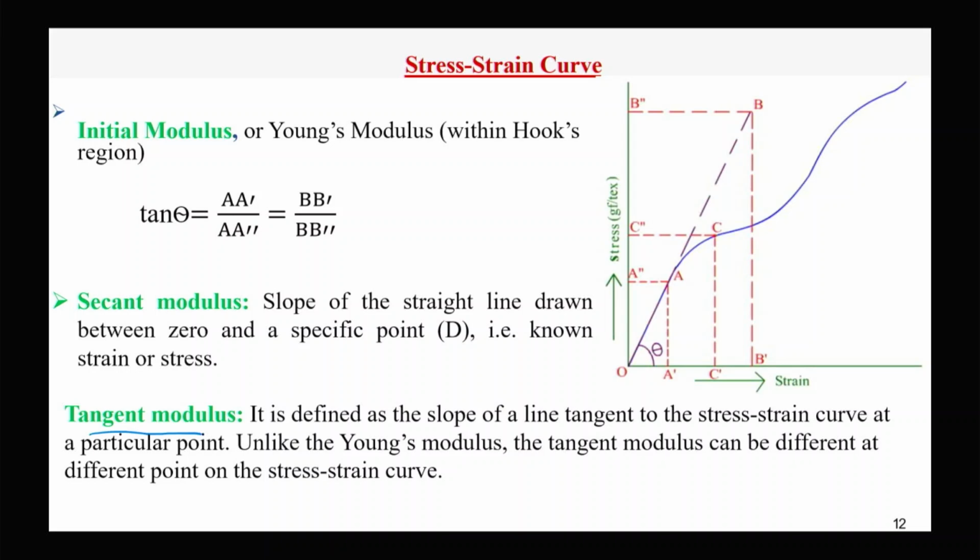Now let us see a material which will be subject to a certain strain during its application. Suppose this strain is at this point, up to that strain it will be subject. At that point, initial modulus or Young's modulus is not going to help. How the load elongation, how the stress strain behavior will take place, how it will actually resist, will depend on the modulus at that point, the tangent of it, whether there will be greater extension after that or not. That's important.